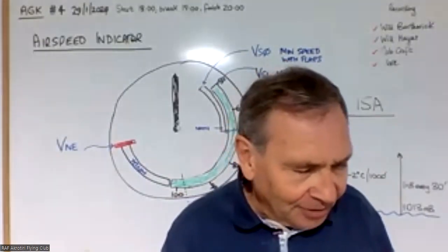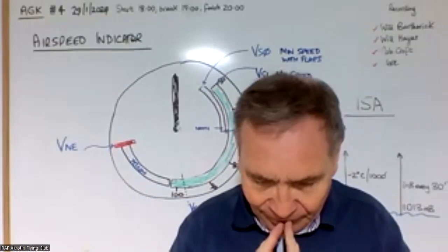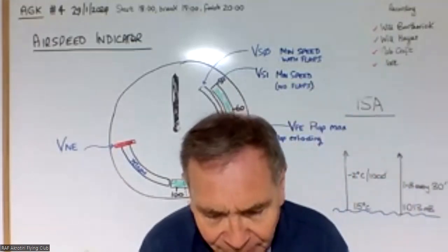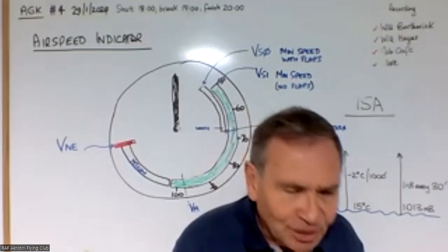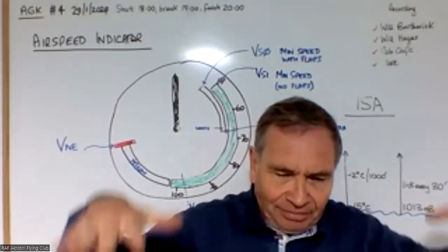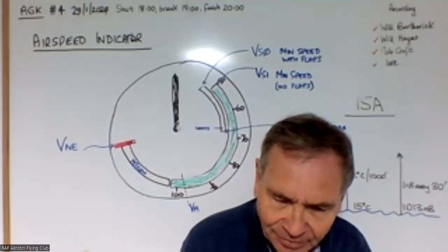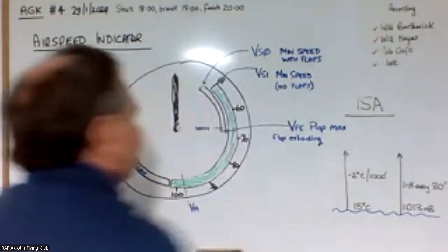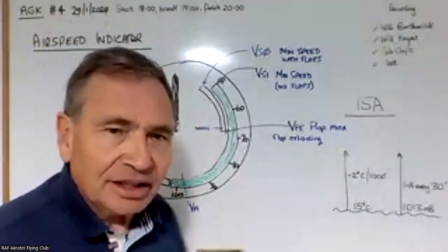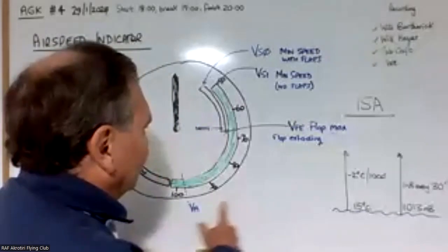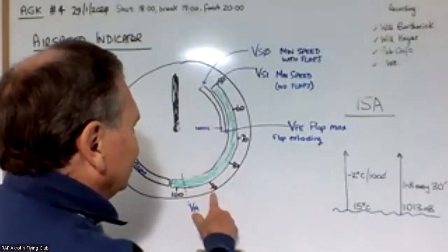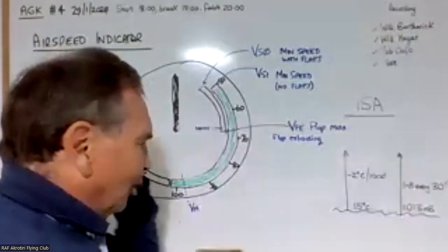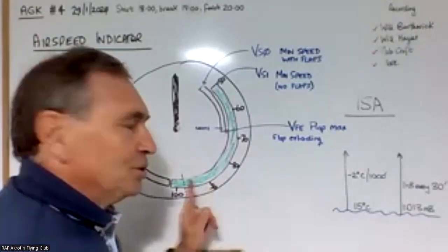So in other words, the amount of molecules per second that's hitting the wings actually remains the same as we climb. So you tend to find that if you're flying along at say sort of like 90 knots and you start climbing and then you level off at sort of 5,000 feet, you'll still be doing 90 knots.